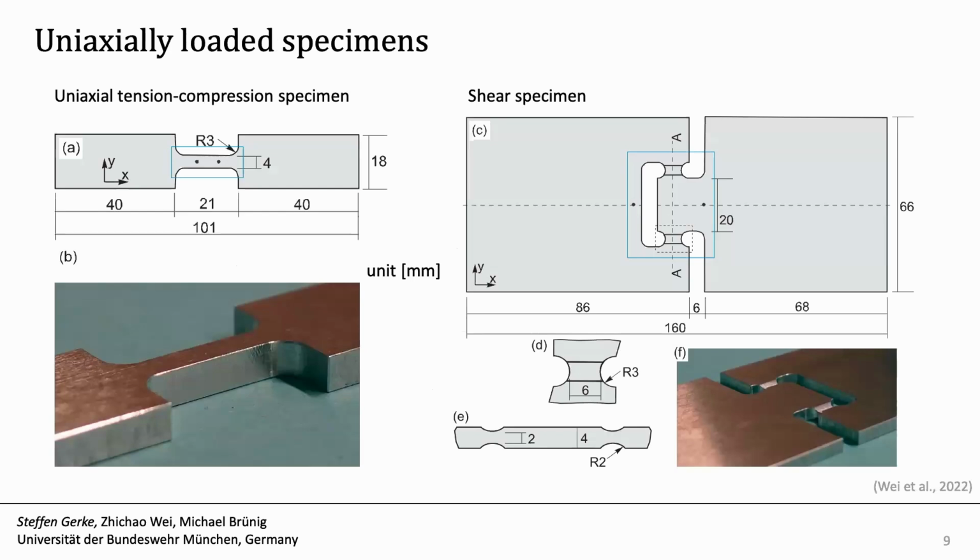Okay, a few slides about experiments and specimen geometries. Here we have the uniaxially loaded specimens. This is what we started out with. We shortened this tension specimen to a very short region, and then we aligned our testing machine very, very well, which means we had to repair it for 6,000 euros. So we could do tension and compression experiments with the same machine to find out about the difference in that behavior. So a very short, very compact region here.